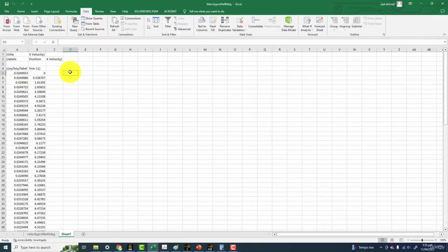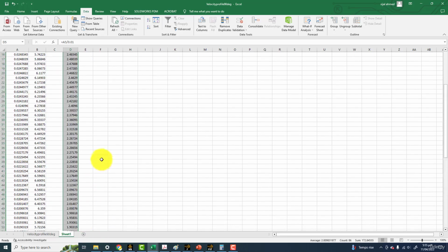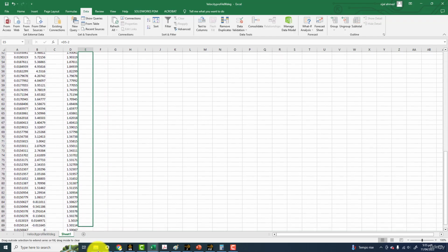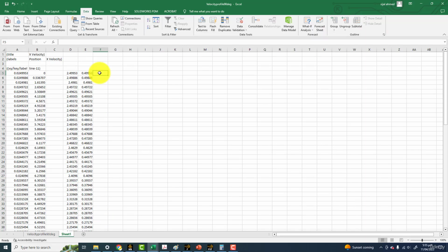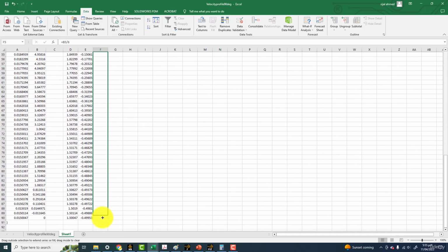Okay, so we have to process data, as you know already. So we have to divide by 0.01. This is the diameter of pipe. And we have to subtract 2 from every data point to make it from plus 0.5 to minus 0.5. Okay, then we have to normalize the velocity by dividing by 6, which is the inlet velocity, and drag it for all the values.